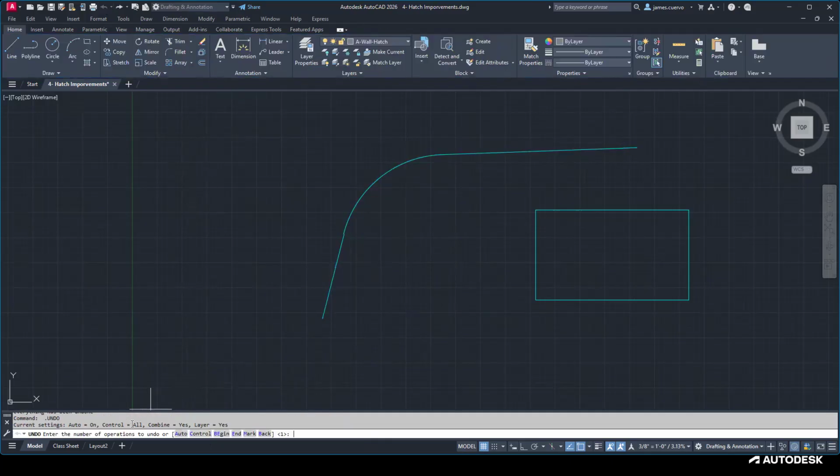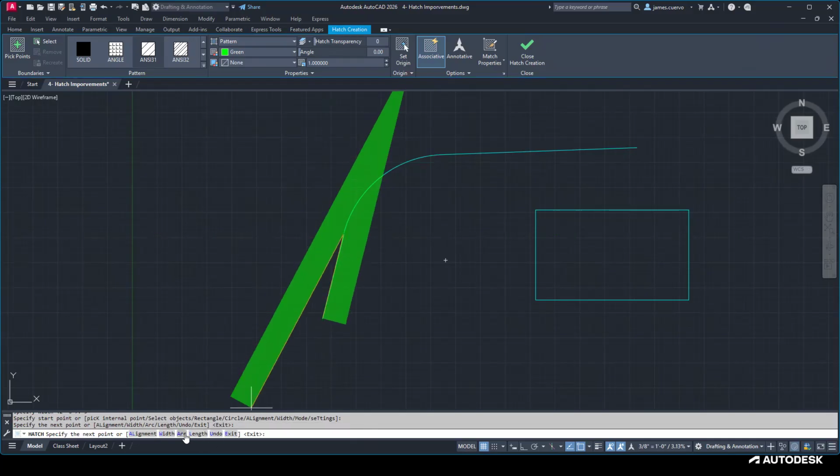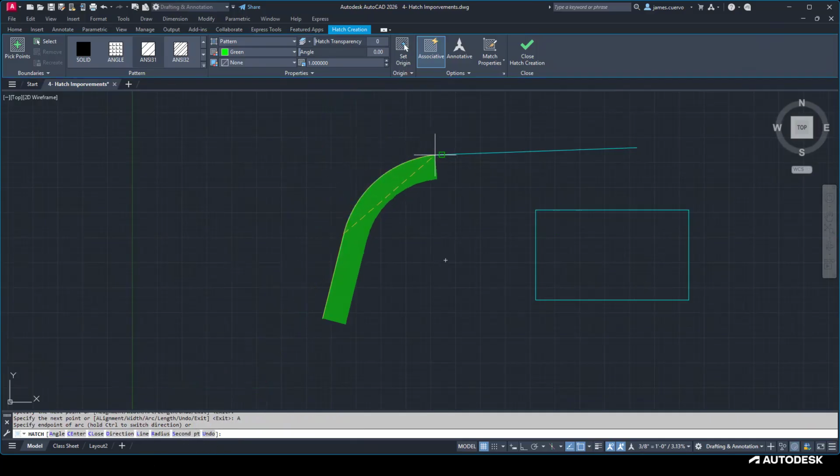So what I would do is call path again. Let's go to Mode again and Path. I would set up my width as we have set it, and then I would start to trace it. Now there is an option for arc right here. Okay, we just set up the arc.